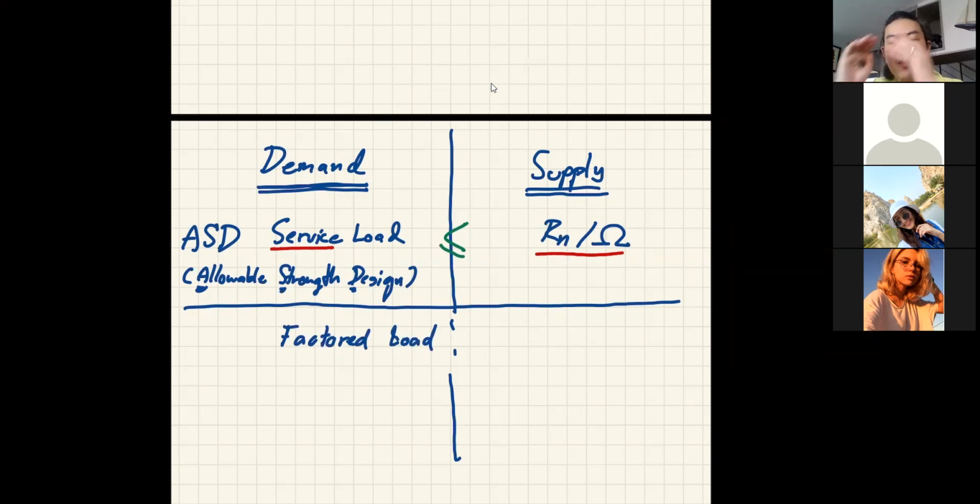Okay, now because you increase the load, you expect to use the actual load, but you account for some uncertainty. So you are going to compare this with the nominal. It's like you use almost everything you got, but reduce it by the reduction factor to also account for some uncertainty, such as if you are going to use the steel hot roll beam, is it actually manufactured to the size that they say?